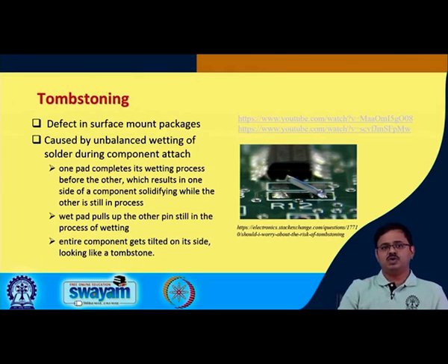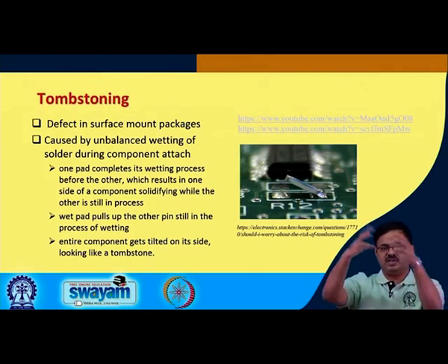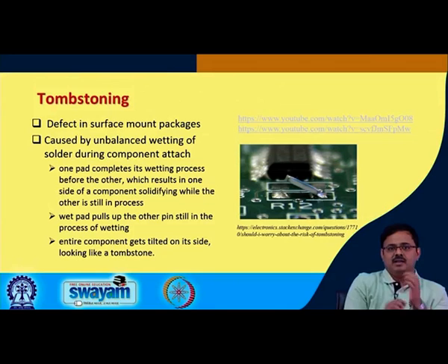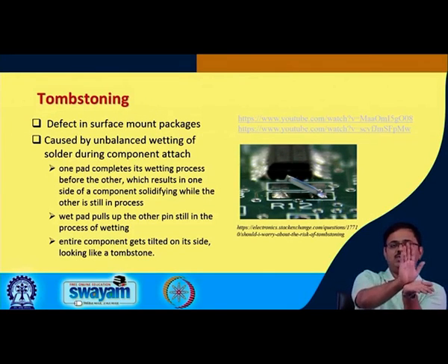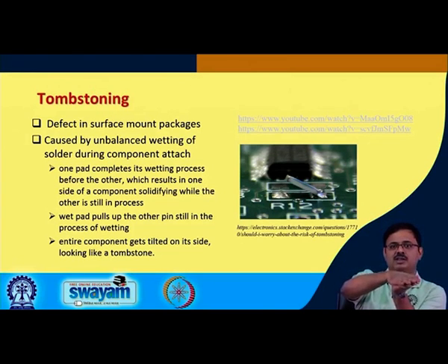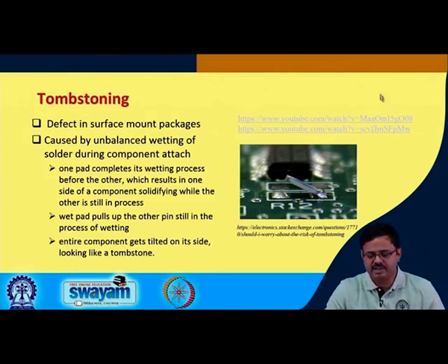just like a tombstone. You know tombstone, where people are buried and you have this stone on top with their names written, some epitaph written. It looks like that, the component is just standing up like a tombstone on the circuit board, where it is supposed to be horizontally aligned and attached on the board. Okay. So, you can see a picture over here.